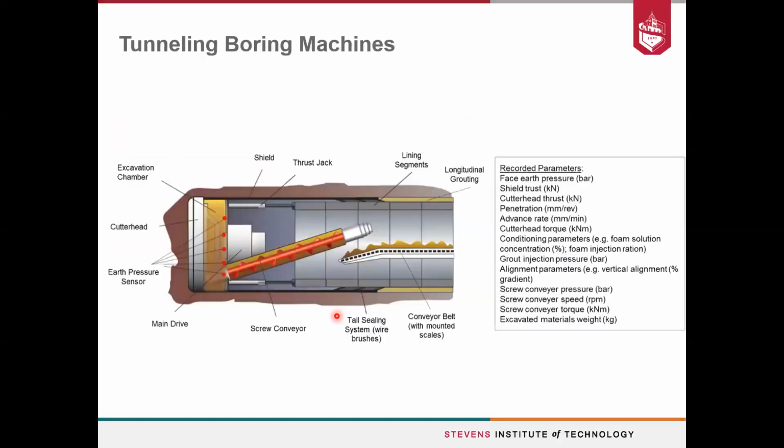So before getting into the details of the methods that I proposed, I wanted to show what a TBM is, right? So this is a sketch of a TBM. And modern TBMs are really highly complex machines where many processes happen at the same time, including drilling, grouting, installing the liners, many other processes, almost like a factory, a moving factory. There are different types of TBMs, and this one that you see here, which is the one that was used in the construction of the Porto Metro that I will show you, is called an earth pressure balance machine.